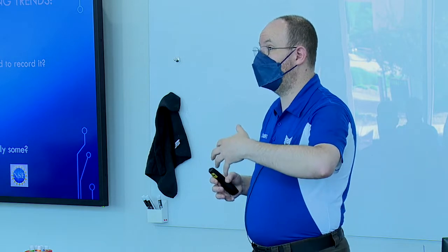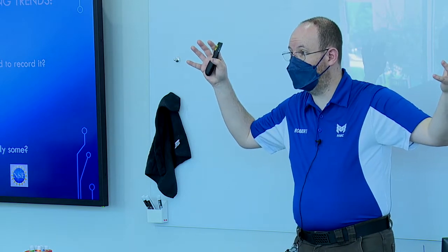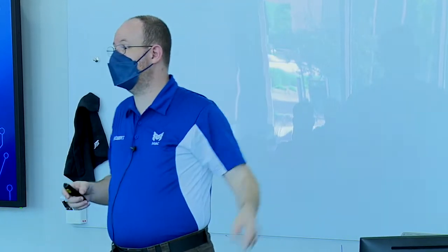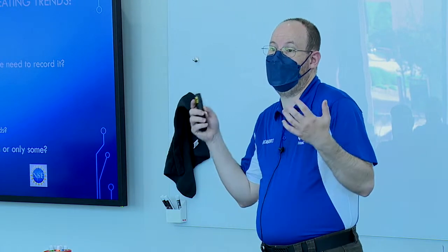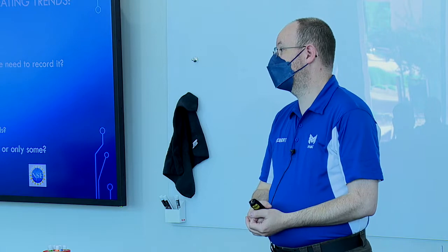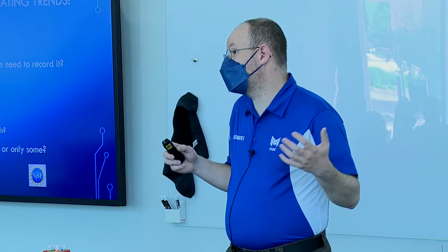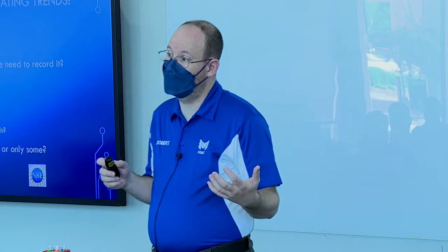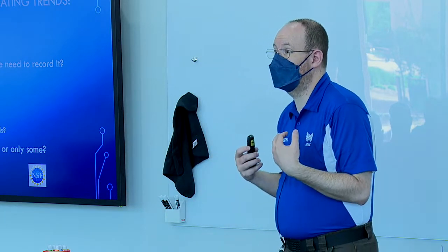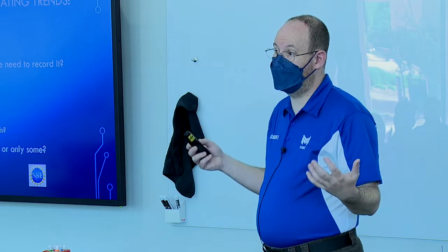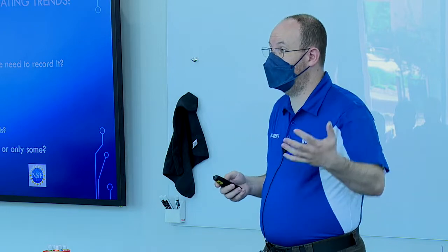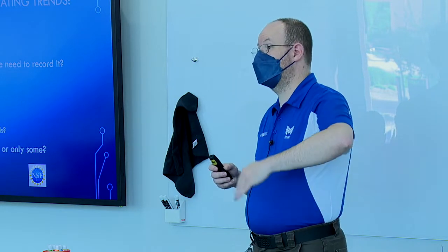Even with this building, which is 5 years old, the MSTP bus in here still runs at less speed than your modem did in the late 90s. When I set up BACnet MSTP networks, I don't care how small it is or how few devices, I cap it personally at 38,000 baud, bits per second, or 38 kilobits, because that's a stable number.